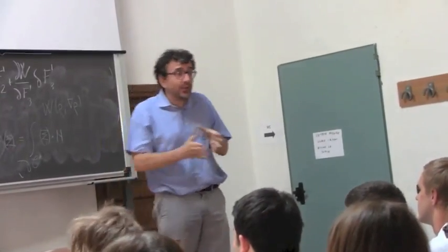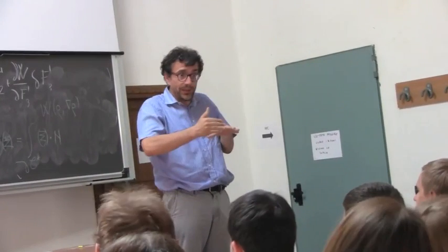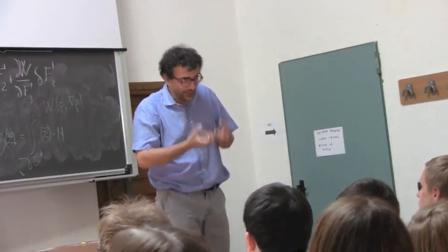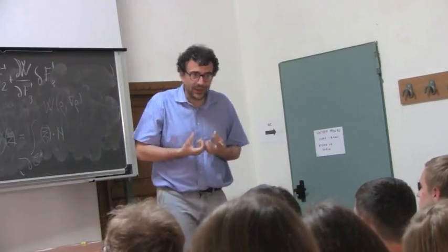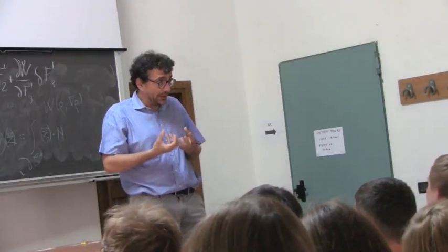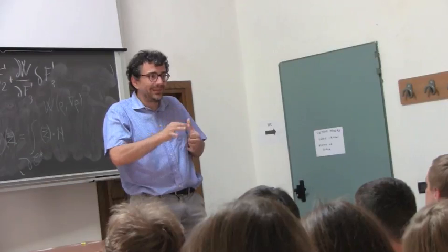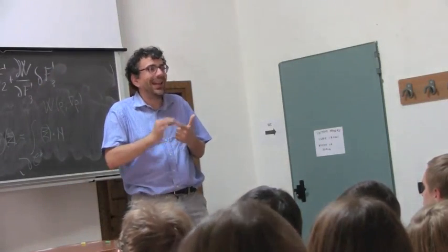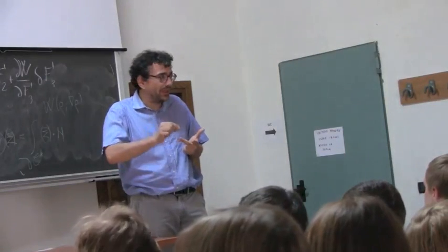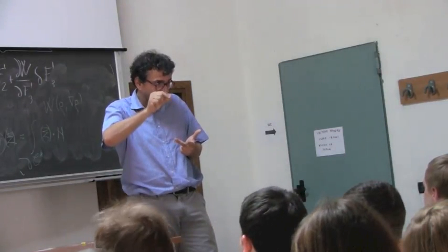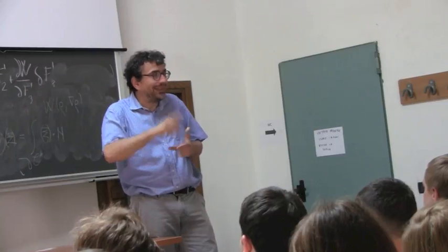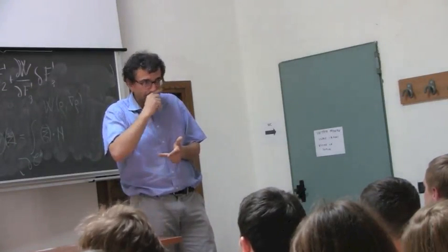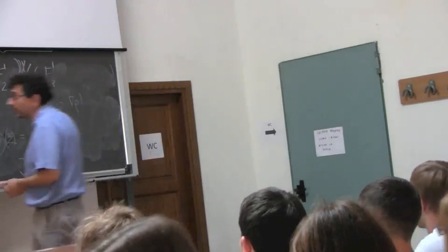Okay? Now I tell you the story. You integrate by parts. I will show you for second gradient, but you must digest it for the first gradient first. Okay? Then we try to attack second gradient integration. You know what you get? You get forces per unit area. This. You get forces per unit line. You get forces concentrated on edges, wedges, so points. But you also get double forces, and triple forces. What are these forces? Angles like this.